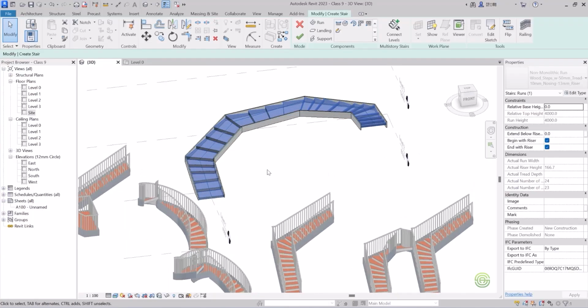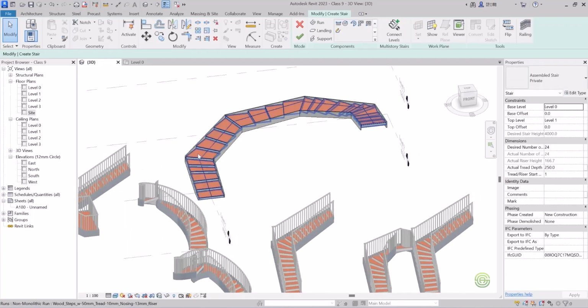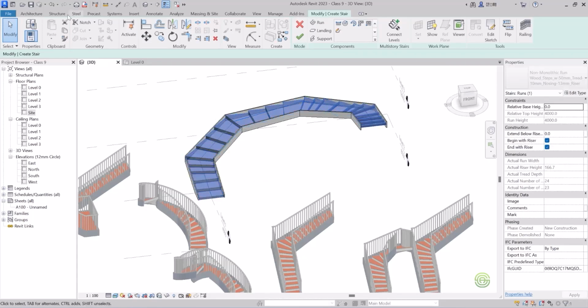Here we can see we have provided a staircase, a unique staircase as we have created. Now to provide railings to this staircase, just select this staircase. So guys, we have to give a green color tick again. We just came out of the sketch, but we didn't come out of the stairs. So we have to again give a green color tick over here. When you give another green color tick, automatically the railings will also be created.